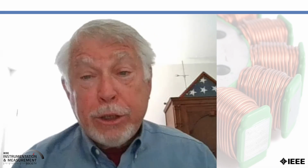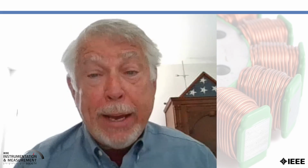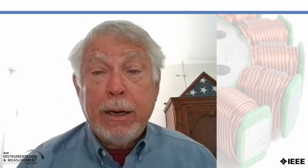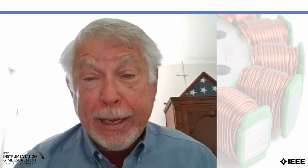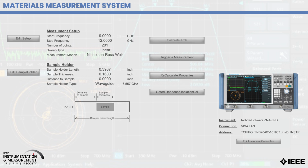In order to do the measurement, I'm going to use an application written in Excel using Visual Basic for Applications to control the network analyzer to do the calculations and display the results afterwards. As you can see, we can set up the start and stop frequencies, the number of points, which model we want to use, and then some sample holder information: the length of the sample holder, the sample thickness, the distance to the sample, and the sample holder type. In this case, it's waveguide, and we've put down the cutoff frequency for this X-band measurement.